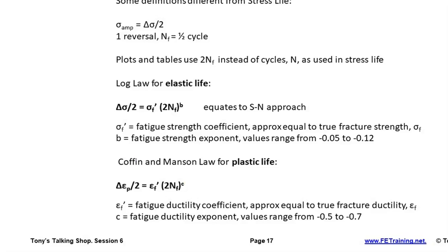we've got a stress strain curve. I'm sorry, we've got a load versus life curve, where we can actually draw strain amplitude or strain range, if we like, and we've got yet another linear curve in log-log space, and we can actually look at the number of cycles to failure down in here. But that relationship is the plastic strain. So that would require a little bit of processing.